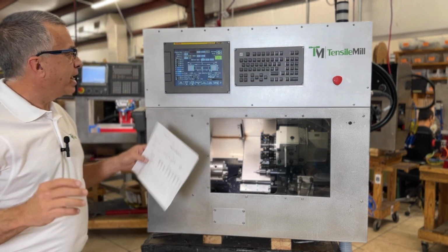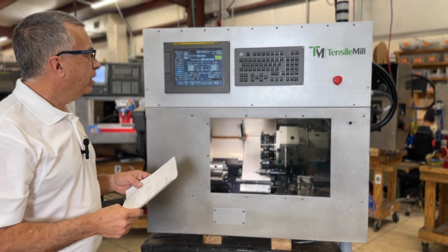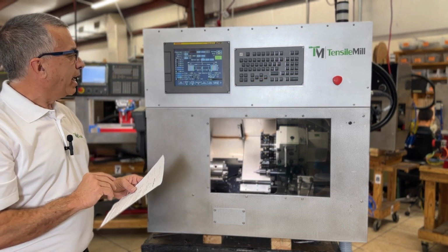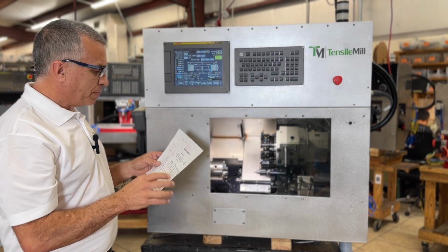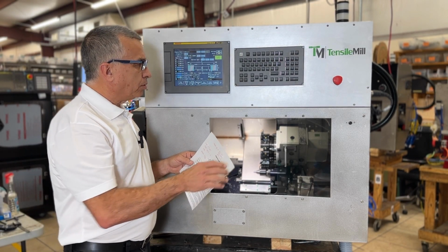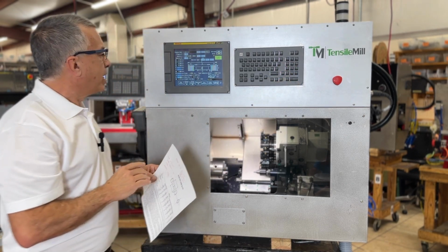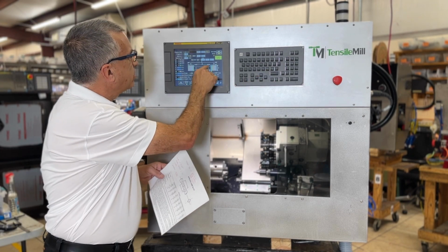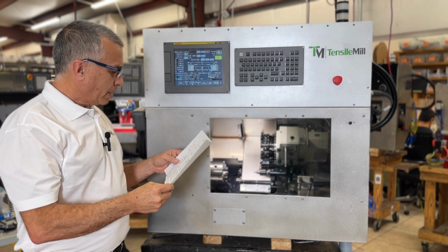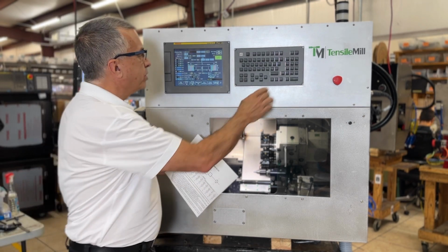The G is the gauge length. We don't use it for machining. It's actually used for the tensile specimen. We don't use it here for machining. L, the total length of the specimen. The total length for the specimen today is 4.5 inches. The radius, the fillet, is 3/8, which is 0.375.